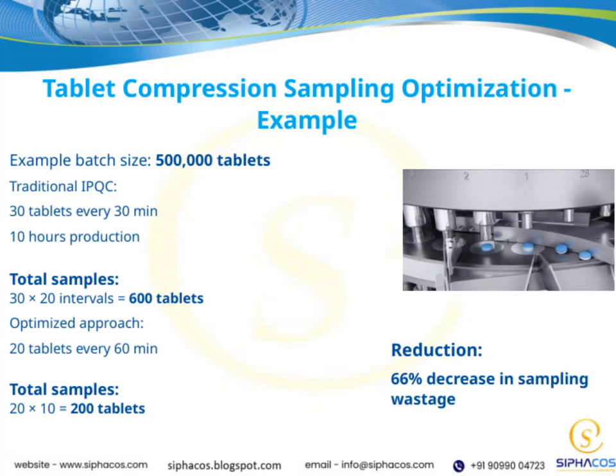Let's take a closer look at the reduction in sampling wastage. We've achieved a 66% decrease, which is quite significant. Now, to illustrate this, we'll walk through an example of tablet compression sampling optimization. Imagine we're working with a batch size of 500,000 tablets. In the traditional approach, we sampled 30 tablets every 30 minutes over a 10-hour production period. That adds up to 20 sampling intervals, so in total, we take 600 tablets for testing.